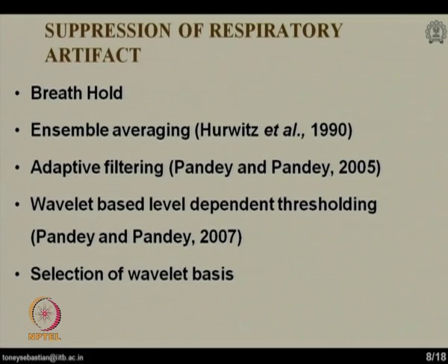Then the next technique, the one we are working on, is wavelet based denoising, known as level dependent thresholding, again developed by Pandey and Pandey in 2007. In wavelet based denoising, selection of the wavelet basis is very important. Why? In denoising applications, whether ECG denoising or ICG denoising, it is observed that if the wavelet and the waveform have a similar shape, then the denoising is always better.